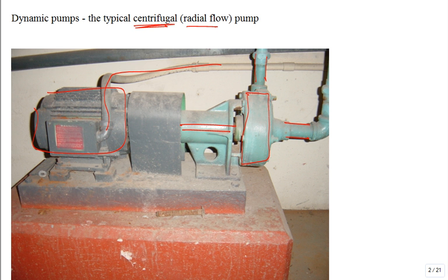Okay, so we know that the electric power is going to come in, and if it's a single phase driving that electric motor, it'd be something like E times I times PF. So the RMS, root mean square electromotive force, like voltage, times the RMS, the root mean square of the current, times the power factor for that motor. And all motors are induction motors. They do have a power factor with it. If it's three-phase, you have that square root of 3, and then similarly the power factor. But this would be the power into the motor.